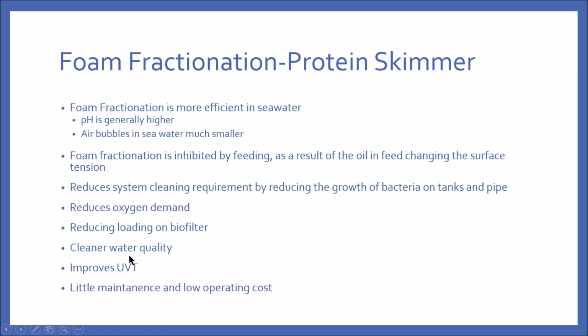Protein skimmers require little maintenance and are generally a low operating cost item. So if you were in a freshwater condition, installing a protein skimmer might not make a lot of economical sense. But if you're running in a brackish water or seawater condition, a protein skimmer is very beneficial to your systems. Note that protein skimmers or foam fractionation cannot replace your drum filter or sand filter. It can only be used as a supplement to the existing mechanical filtration techniques, as it remains a polishing method to remove any fine solids and big protein molecules.